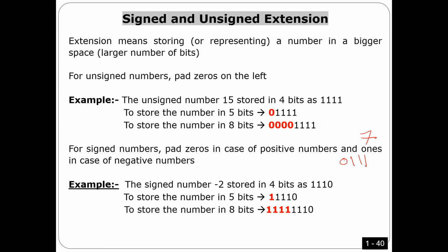Luckily, what I said is true, accurate all the time. You need hardware for signed numbers, hardware for unsigned numbers. However, we have one exception: addition. In case of 2's complement, I can use the same hardware for unsigned and signed. Only in case of 2's complement. That is why people like 2's complement. As an exception, in the 2's complement system, the same hardware can produce the correct result, it doesn't matter if the input is signed or unsigned.